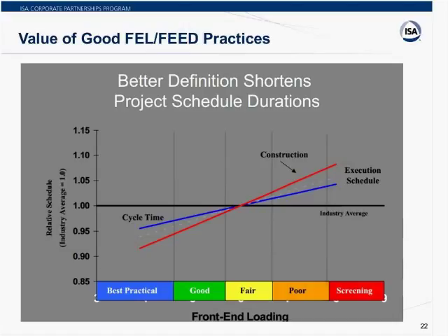Again, I think when we talk about high-performance graphics in this presentation, that's known as many things. There's human factors, human-centered design. The ASM Consortium has published more information on this than others. But if you look at those graphics, this is the grayscale, color-by-exception type of graphic. The characteristics that are very common are that information is presented to the operator by exception only. So color is used to draw action.